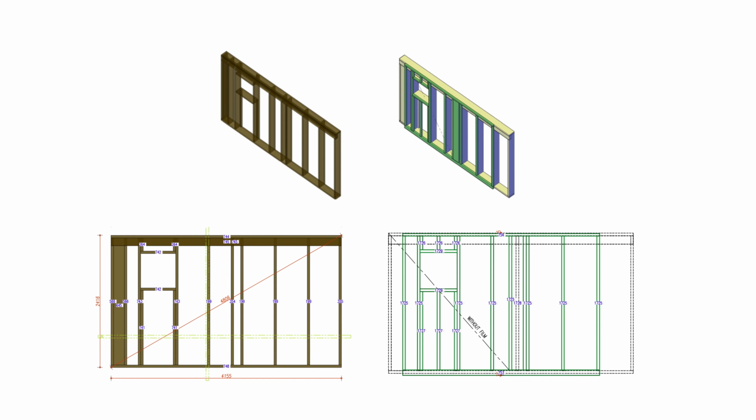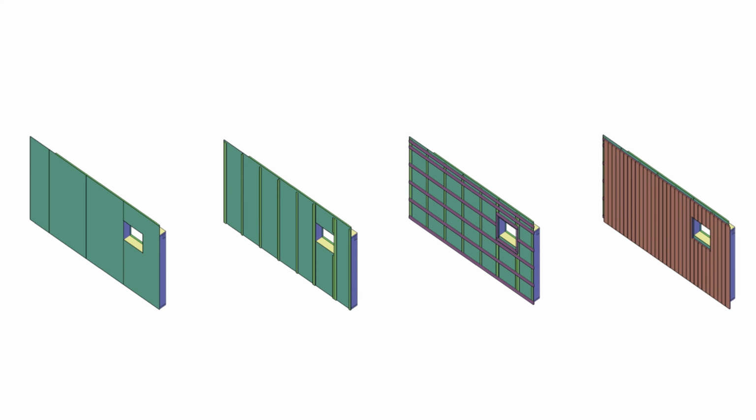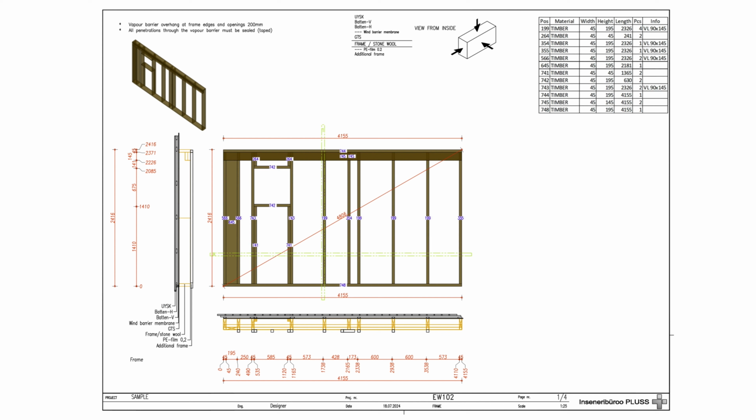In this case, it is not necessary to turn the frame over in advance to install the next layer on the work table. If all the layers on the room side are compiled, then the element is turned over and the layers of the exterior side of the element need to be installed. By understanding these principles, it is easier to understand more complex production drawings.